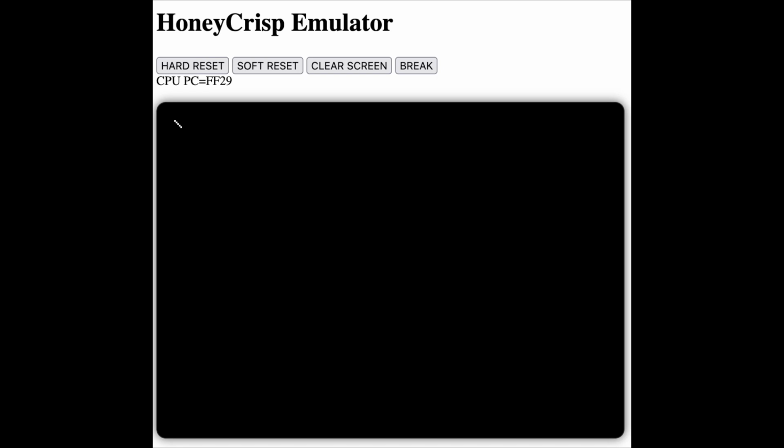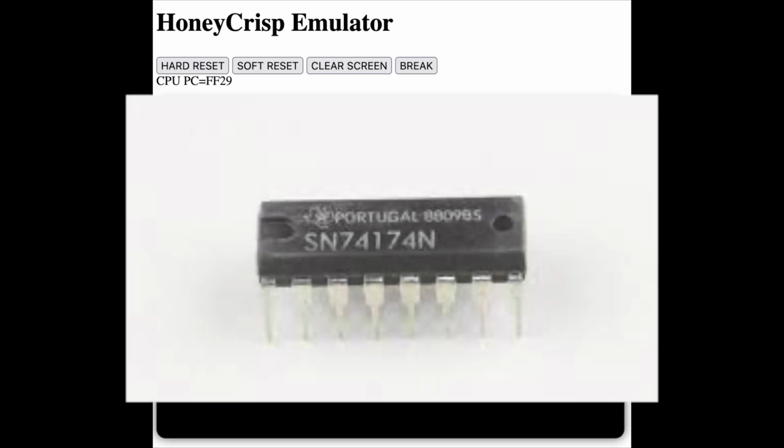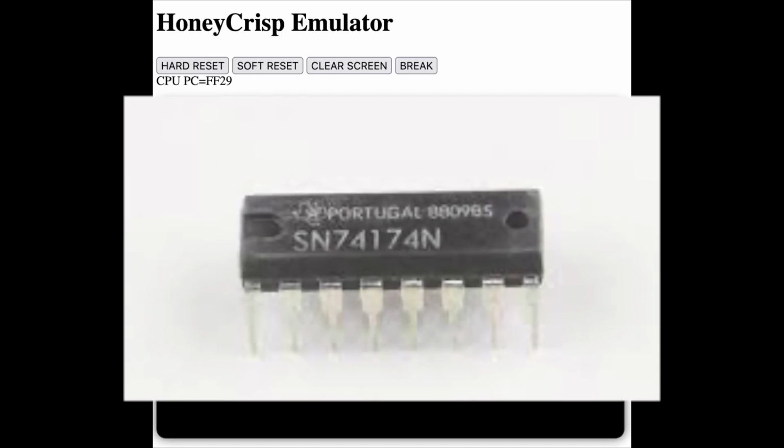In my most recent iteration of HoneyCrisp, the change I made had to do with the Apple-1 character set, specifically the Signetics 2513 character ROM. You see, the character ROM that I was originally using in my previous iteration of HoneyCrisp was incorrect. It had a ton of glyphs and characters that weren't originally supported by the Apple-1.